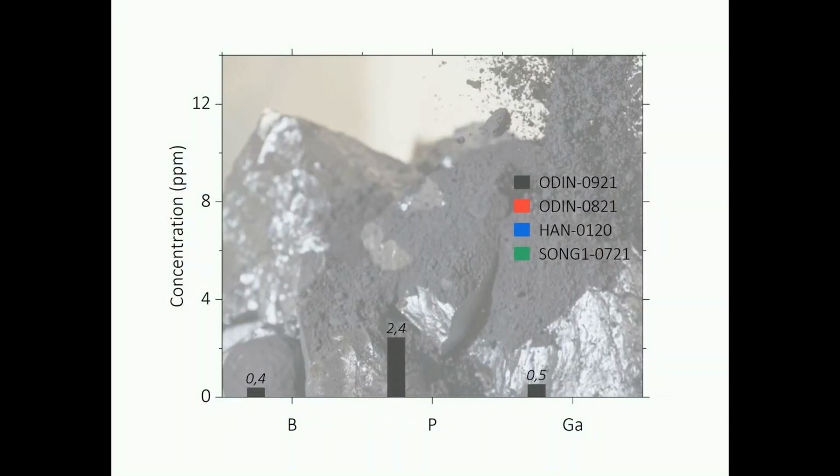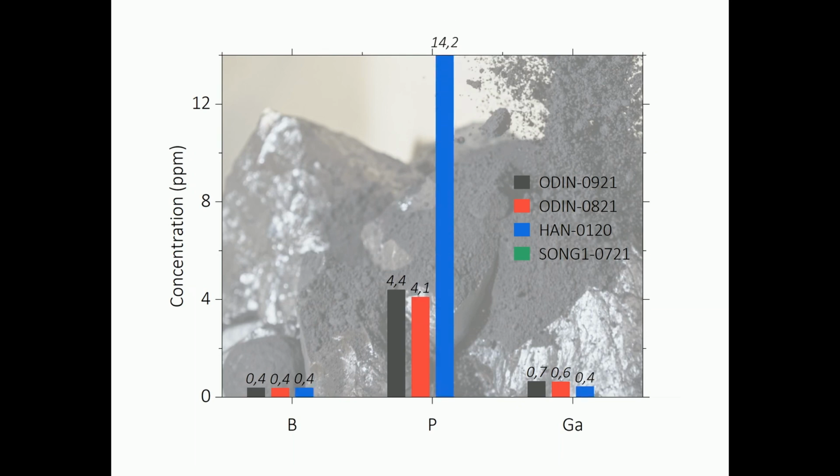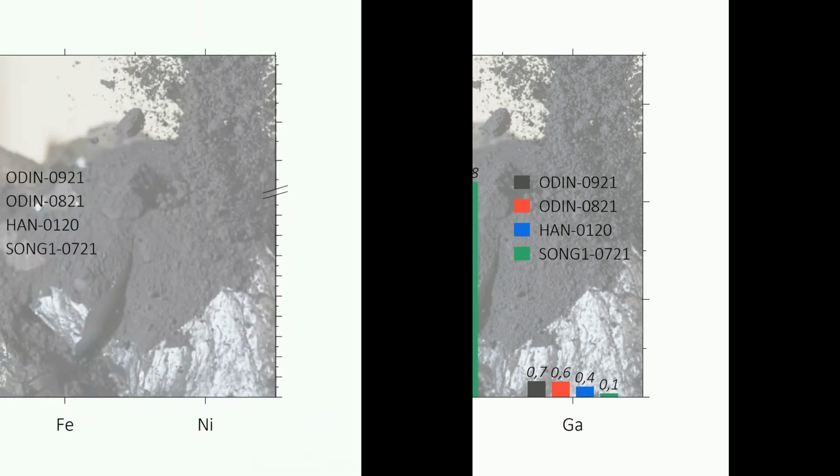Common doping elements used in silicon ingot production are boron, phosphorus and recently also gallium, which are again present in the silicon kerf. Additional dopant contamination sources for phosphorus are from the glue and beam materials used in wafer sawing.